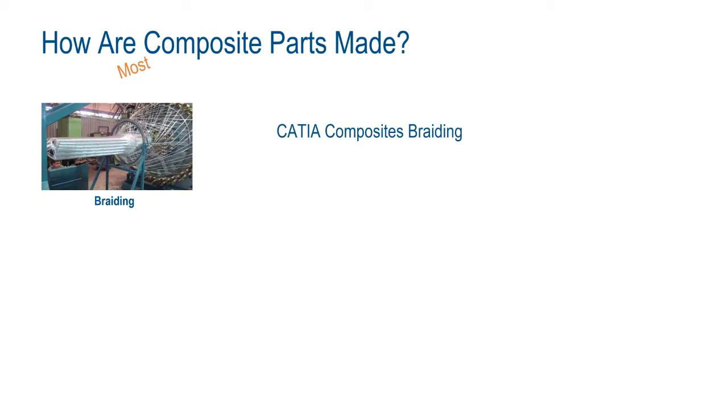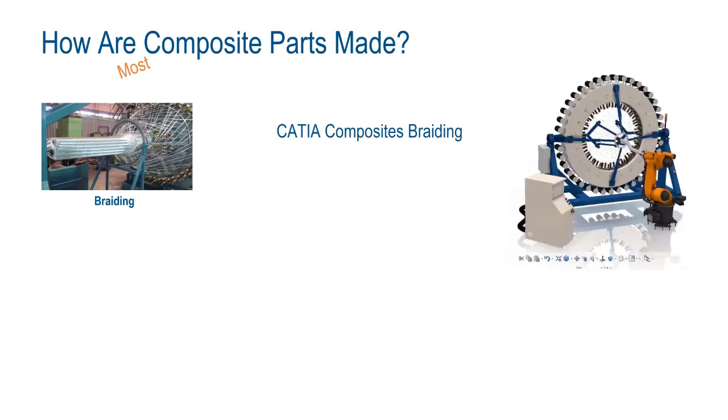This is technology that provides the ability to simulate the radial braiding process, and I have an image here coming out of the application showing what that looks like. For anybody not familiar with this, these types of parts are made by interlacing multiple yarns over a mandrel. Ideally that mandrel would be robotically fed through a braiding machine, and around the perimeter of it would be an array of carriers for multiple strands of yarn, which is what is shown.